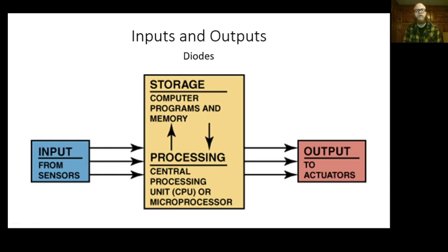If I want to roll the window down, the first thing I'm going to do is push a switch. If I want the headlights to turn on, the first thing I'm going to do is turn a switch. If I want my vehicle to start up, I'm either going to turn a key, which is a switch, or push the little stop-start button on my dashboard and my vehicle will start up. So switches are probably the most common input that are used, especially in body electrical for sure.